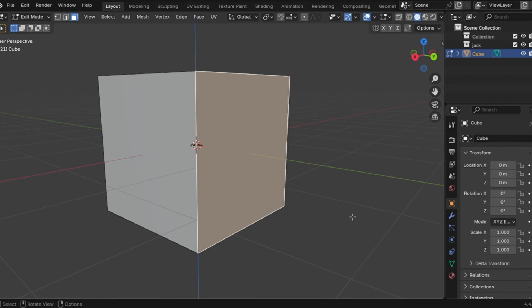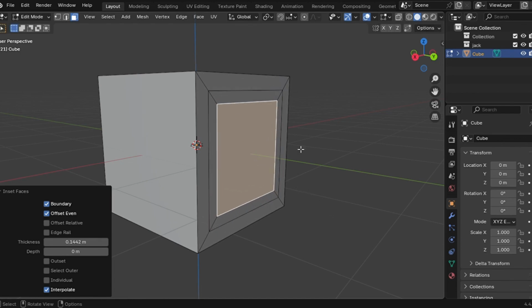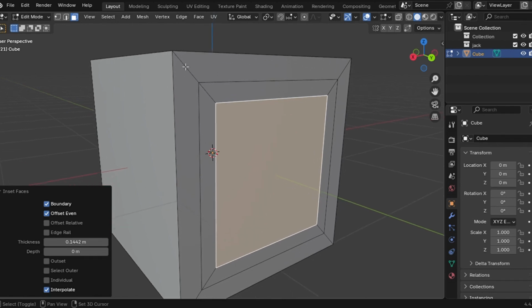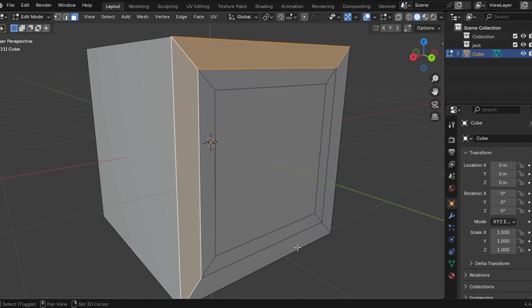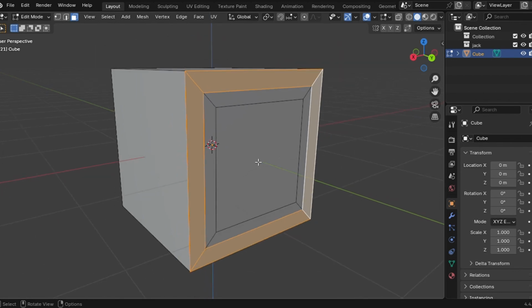And the next method, which I think will make it into one face, is by selecting everything. So here's a tip: if you're in a loop, for example, this is a loop edge. Notice that it has a loop. If you want to select everything one by one, it's going to be really time consuming. This could seem easy because I only have 4 edges, but if you have 50 or 60 edges, it would be really hard to select one by one. So in that case, you hold the Alt key and click on the middle portion.